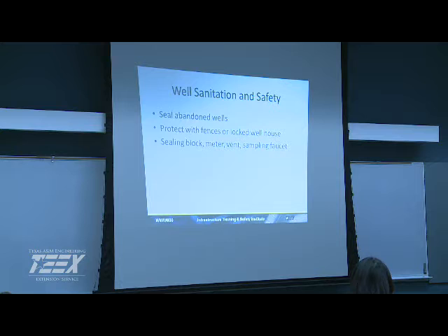There's some real big projects, even one in San Antonio, military base. Their disposal method, especially for a lot of their organic solvents, was to dig a big pit, put it in the pit, and hey, it disappears. Great. That was a shallow water aquifer in there. And so now they're pumping it out on their downstream gradient, treating it, and pumping it back in upstream and helping the gradient head move a little bit faster. That's happening a lot.